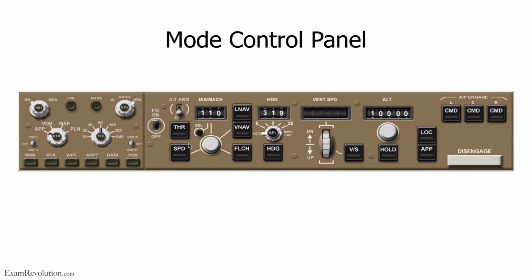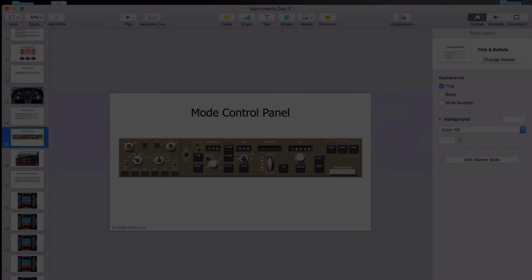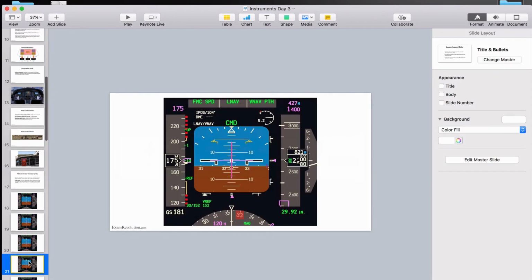Now the flight director is going to show you what you must do to fly at 140 knots. Now guys, remember, here you're still flying by hand, right? We haven't put the autopilot on yet. The autopilot is off, so you can literally pick certain settings, and you can just hand fly the aircraft into the flight director, and the flight director will show you what you must do to be where you want to be. So if you want to fly 140 knots, it's going to show you what you must do with the aircraft to get to 140 knots, right?